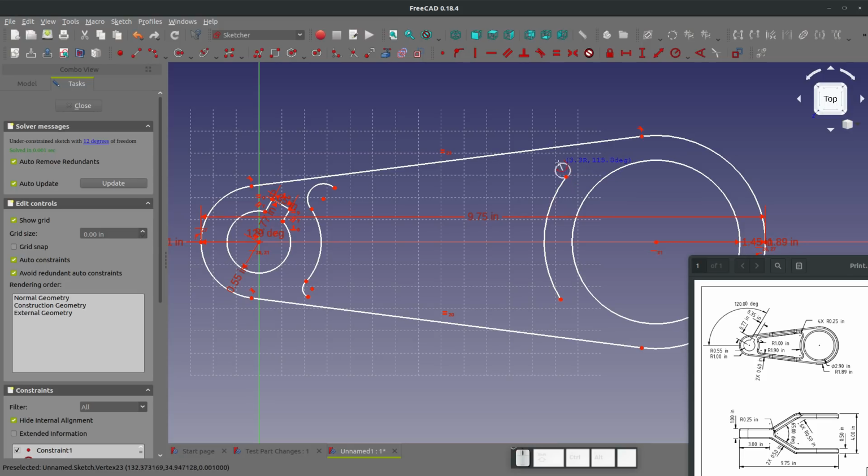And we're going to grab, this is a total of 6 arcs. I'm going to hit T for tangent and click on each arc to make sure that they are all tangent to one another. And then I'm going to get an E for equal constraint and make sure that every arc is equal to every other arc. And then let's draw a line from here to here, and here to here. Tangent, again, and I'll make sure that we're tangent to the line.